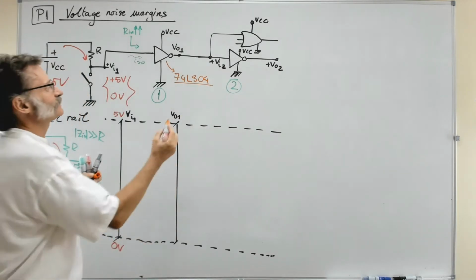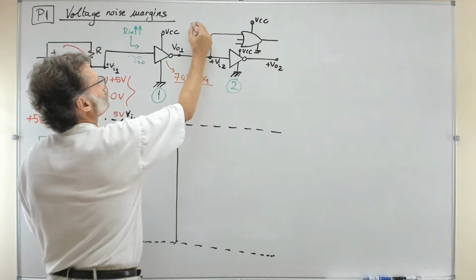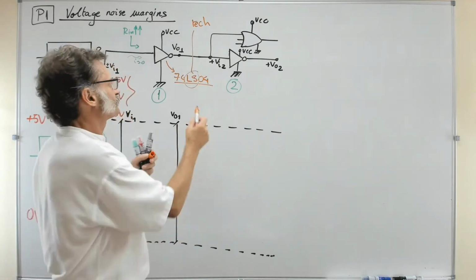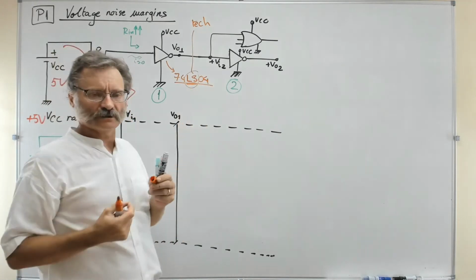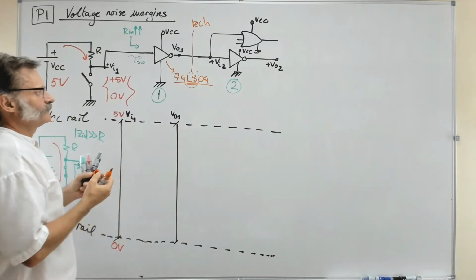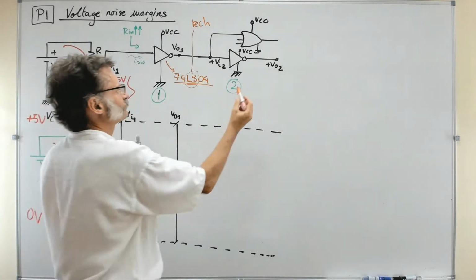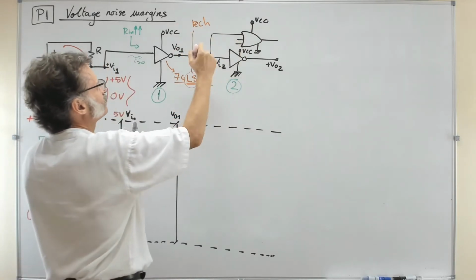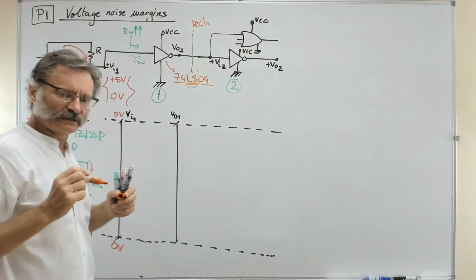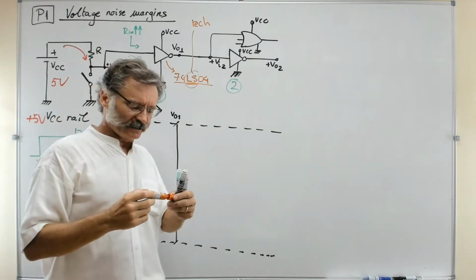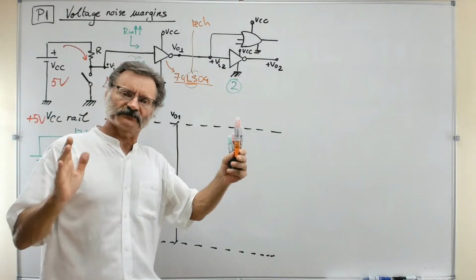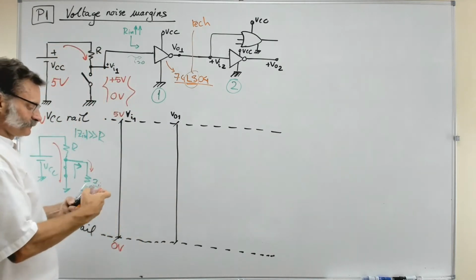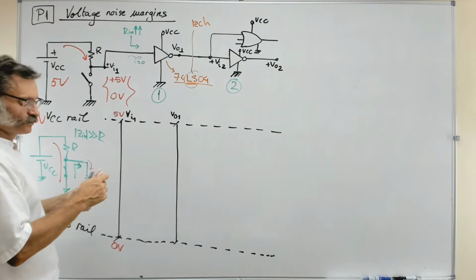But you know, this is already a digital technology, and all the chips of the same kind, LS, low power Schottky, are of the same logic family. So this gate has to be of the same family. This is what is called the logic family, and the logic family is associated to a given set of characteristics. And these characteristics are going to look like this, you see.